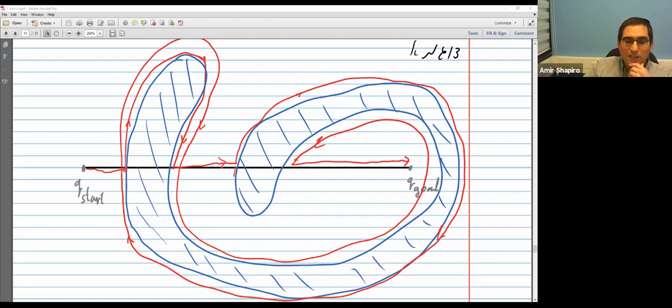Here I chose to go left at each time, so I go left, I go here, I hit the line again, then I'll go here, I find another obstacle, I go left again, I go back along this, as you see, go all over again, until I won't stop here because I already was here and this is not closer. I didn't get closer to the goal, so I won't stop here.